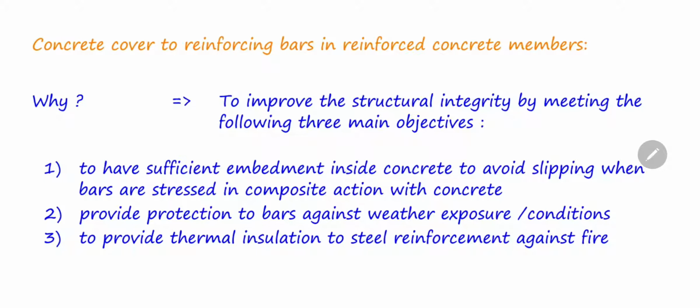First of all, let's discuss why we need to provide concrete cover to the reinforcing bars. The main purpose of providing concrete cover to reinforcing bars is to improve the structural integrity by meeting at least three main objectives. Number one, to have sufficient embedment inside concrete to avoid slippage of bars when the bars are stressed in composite action with concrete. Number two, to provide certain protection against weather exposure conditions. Number three, to provide thermal insulation to these bars against any possible fire.